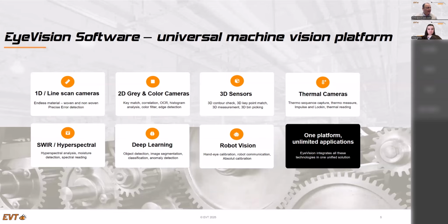That's correct. Yes, also for line scan cameras, to come back to the original thing. Also for line scan cameras, normally GigE is fast enough for the average line scan application, up to 60,000 lines per second, depending on the number of pixels the line scan camera has. Gigabit Ethernet connection is still fast enough.